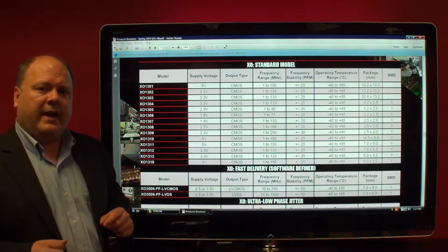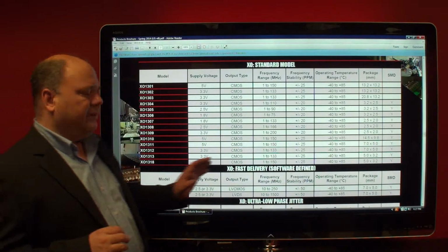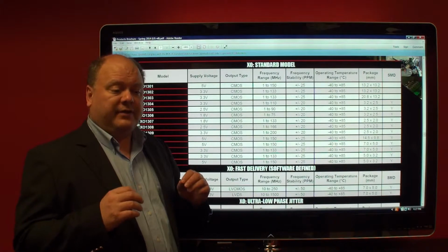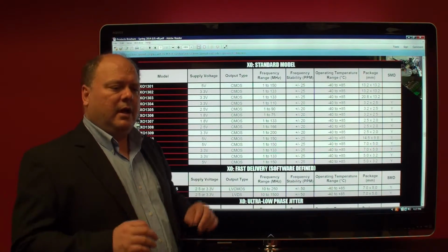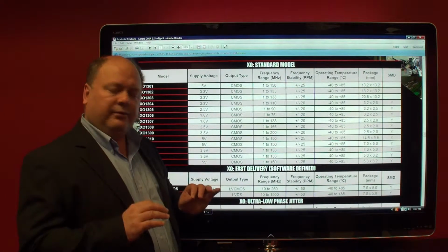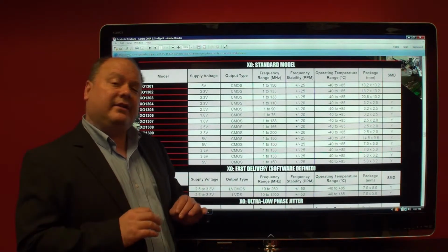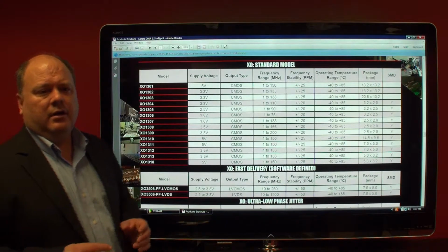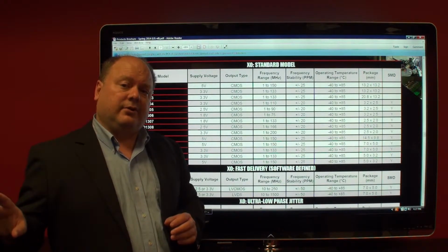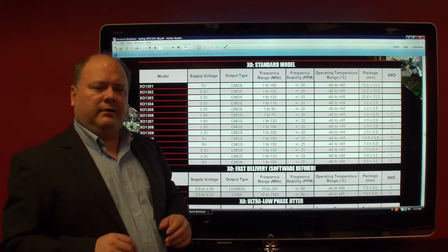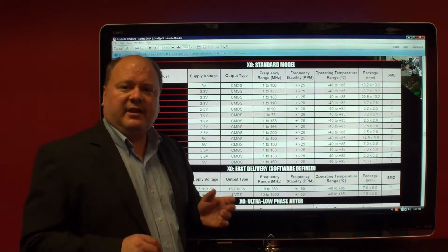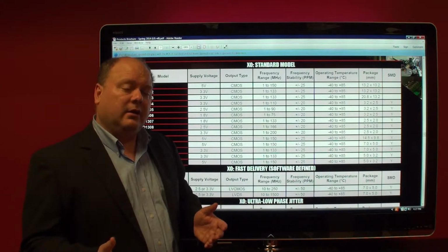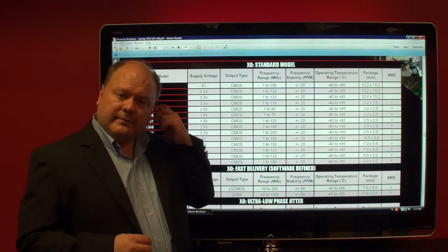What I mean by that is internal to the design, our factory, our office, depending on who has the programmer, can, through software commands, create a discrete frequency, any frequency the customer wants, out to 6 digits of resolution. So 13.666666 megahertz, we can generate that frequency clock. We can ship that in under 2 weeks.